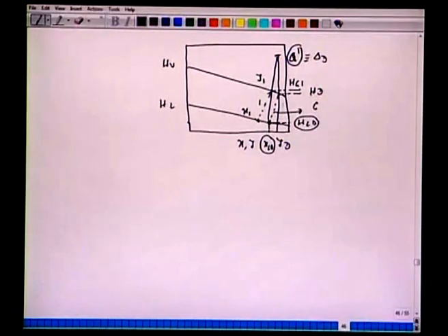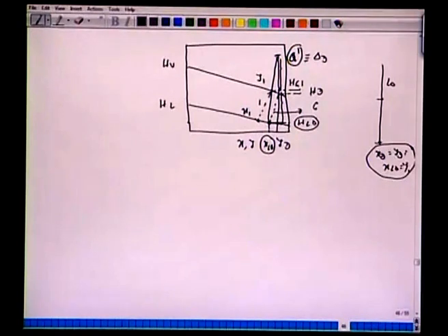This reflux ratio must be obtained from this segment here and here. Notice the difference in the total condenser: we used to have L0 and D, right, from Xt equal to YD equal to XL0 equal to Y1. So, the construction for the partial condenser and the total condenser is different.